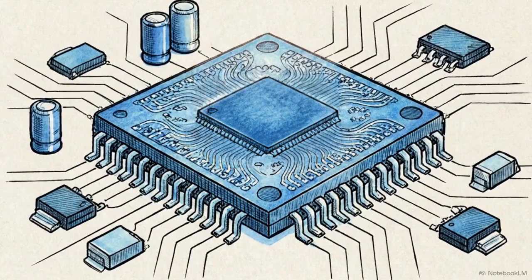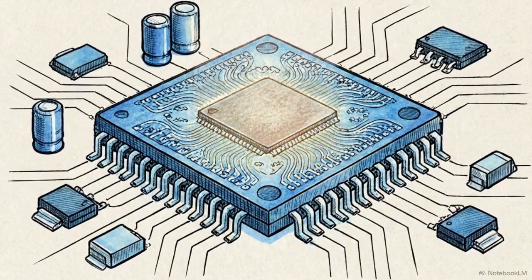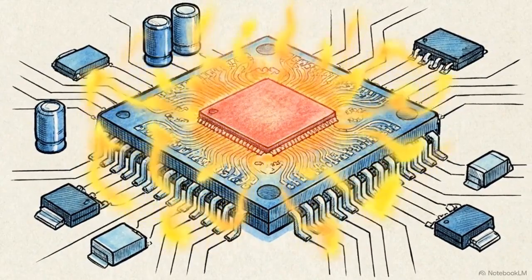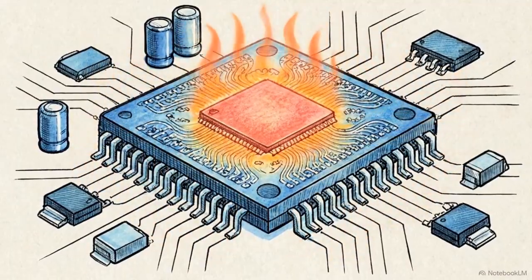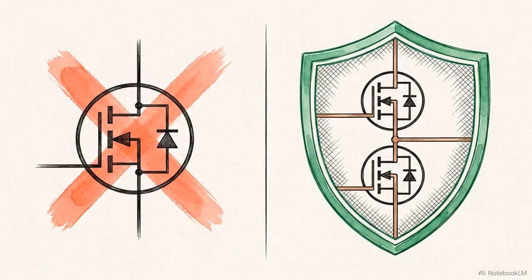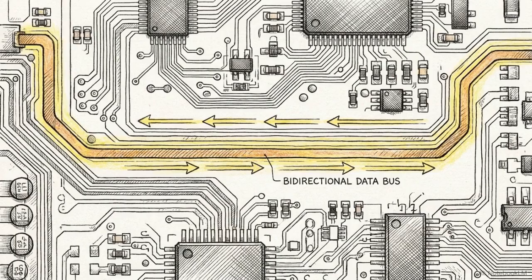Small timing errors lead to high-frequency switching losses, which significantly increases the heat the cooling system must dissipate. To operate efficiently at these speeds, standard switching protocols are abandoned. The system uses a hybrid modulation strategy built on back-to-back bidirectional switches. Interfacing the secondary active bridge with an AC grid introduces a strict physical requirement. The circuit has to block voltage and conduct current in both directions.